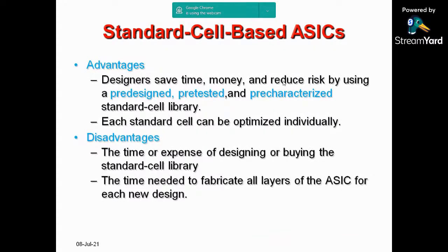So, the advantage. The only thing is, when I want to go for the standard cell approach, I need to buy the cells. Buy from the library, right? Library in the sense that there are companies which actually sell all these pre-characterized and tested cells. So one has to buy it and use it. The only thing is expense, of course, in buying the library. But once you buy, you can do a lot of designs, right?